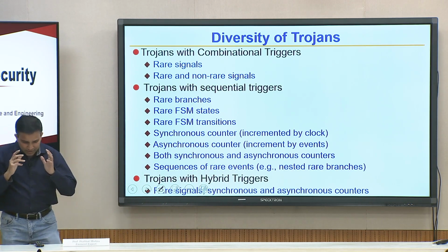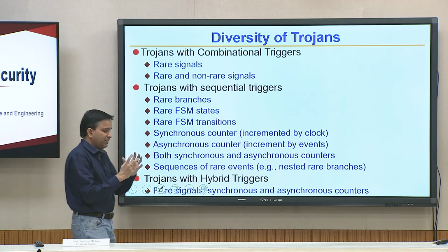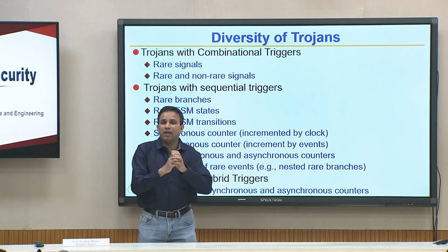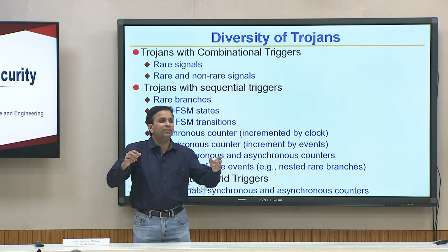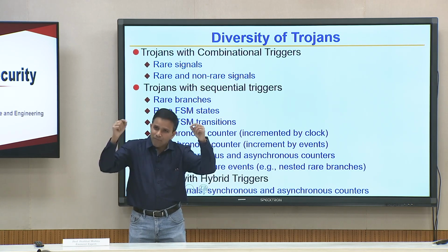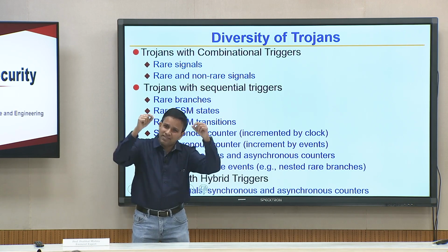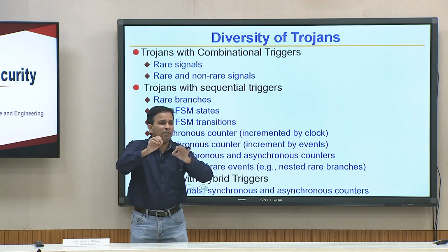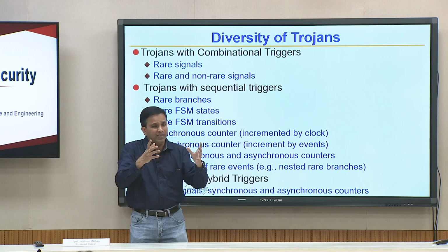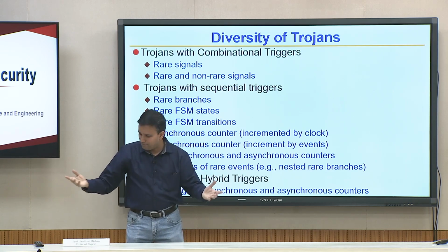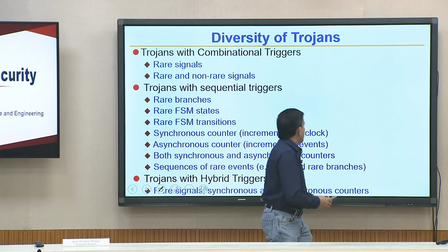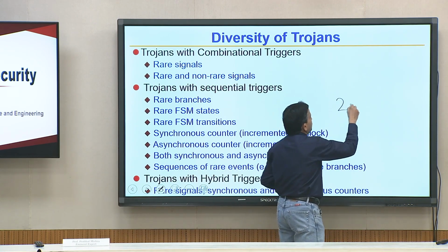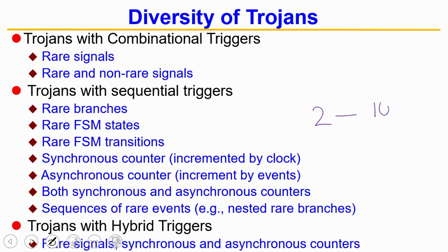Number 2 is the notion of process variation, because each of the gate, the amount of power they consume or exact area, it is not identical. If you create millions of AND gate, same fabrication technology, same day, same time, they will have minor, very small variation, but if you multiply that by million, then you are looking at a number, people say 10-12%.